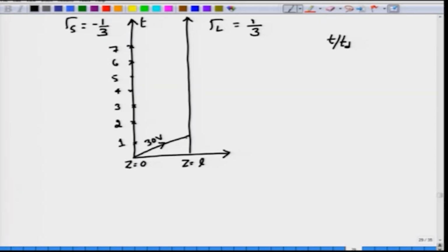Now, what will happen as this voltage arrives at the load? When it arrives at the load, the essential circuit that it is seeing is something similar to this one. So, you have a Z0 and then you have a ZL here. We do not really need to connect this one, and this will not be a voltage divider kind of a thing, unfortunately, because you have to deal with gamma L as well as the transmission coefficient tau L, which is what I am going to tell you in a minute now.